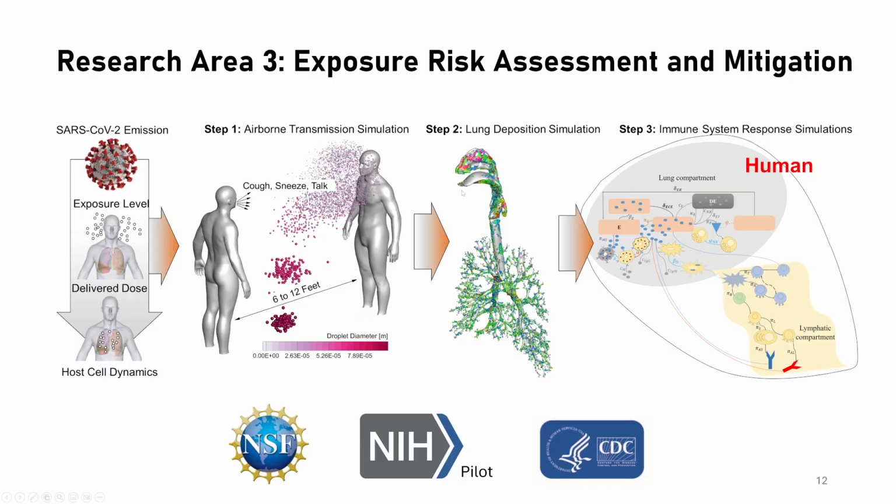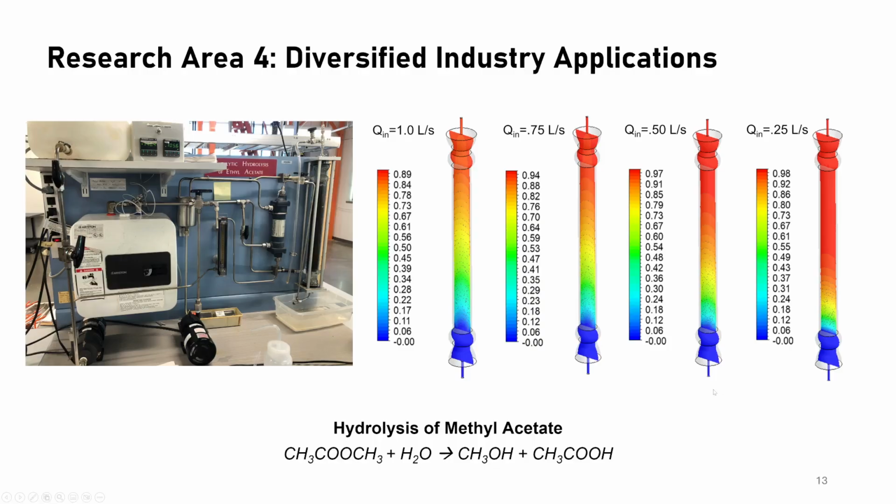We definitely, like I said, use this kind of virtual human model to do exposure risk assessment, and I just want to show you the workflow that we are doing. But also, talking about applications, I'm a professor in chemical engineering, so I would like to apply computational fluid dynamics to prediction of different chemical engineering processes, right? What you can see here is one of our unit operation labs, a packed bed reactor. Connor and I built this 3D packed bed reactor digital twin, and we ran different flow rates and different temperatures to see how the hydrolysis of methyl acetate is influenced by these factors.